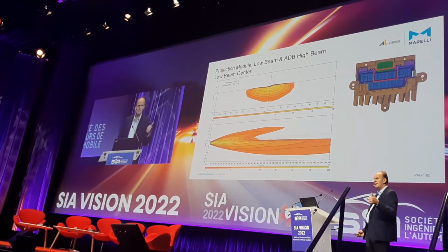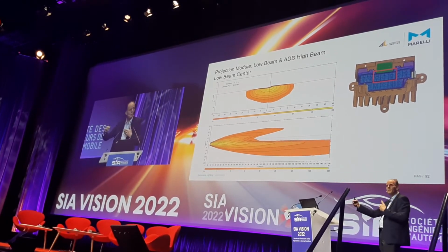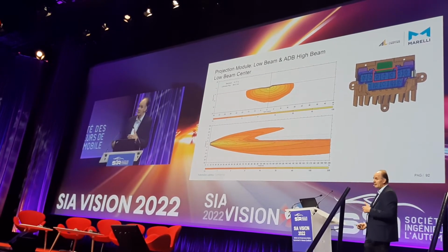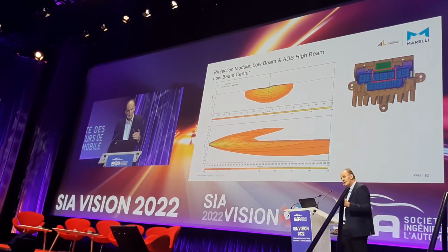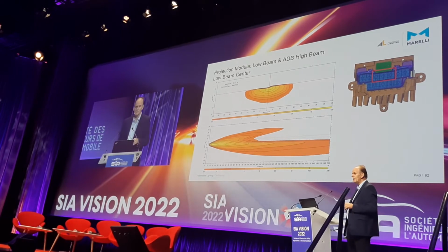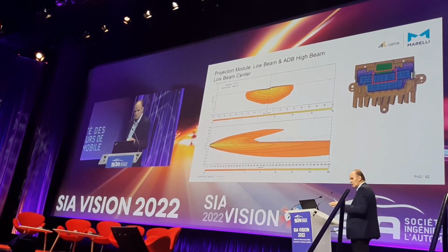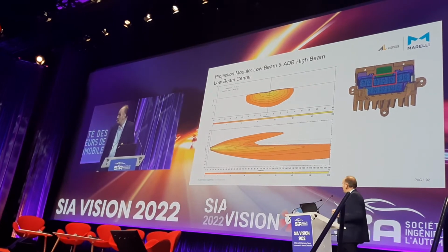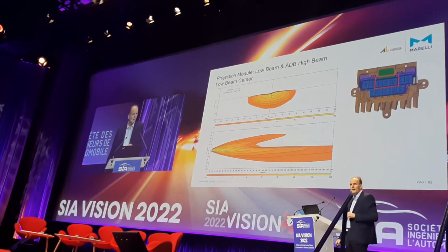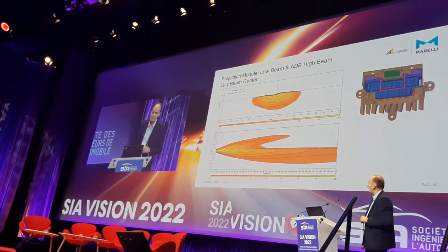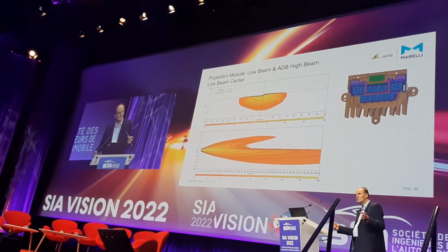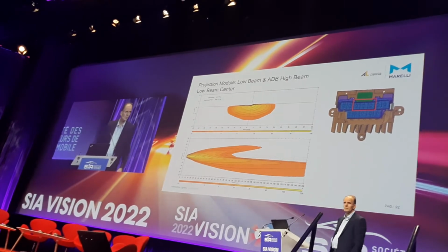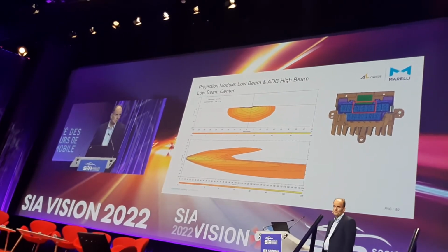Depending on speed, the traffic situation, and other levels of illumination, we should think about giving the driver the right level of lumens on the road. But we should not boost 900 lumens, roughly 40 watt, to the road if there is street illumination which creates 3 candela per square meter.